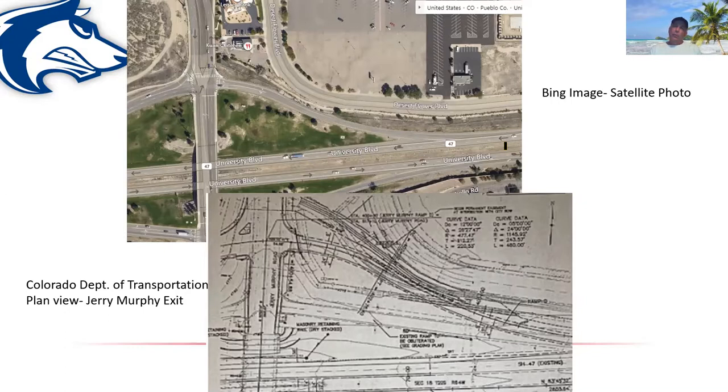So between this straight piece and this straight piece, we would come in with some sort of a curve that would slowly transition from this tangent to this tangent. Right here would be an example of where that information is given in the set of highway department plans, this being the center line of the road.